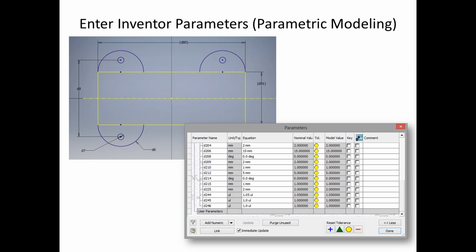So looking at the basics of this, the first stepping stone, that's where the inventor parameters come in. The term parametric modeling actually stems from those inventor parameters. Every numerical value you put into your sketch or into your feature, whether it be a linear sketch dimension, an angular dimension, a radius or a diameter, an extrusion length, a revolution angle, or even a pattern quantity. All of those numerical values become parameters that you can push and change and reuse, and the reuse is where the properties come into play. So there's a nice domino effect of how all this kind of changes together.